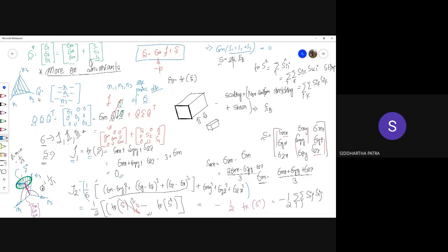So it's not the same octahedral plane, because this time we are not talking about microstructure. This time we are talking about a macroscopic representation. But again, the amazing thing is that in relation to plastic flow, in relation to plastic deformation, we are again stuck with one octahedral plane. It seems that the octahedral plane has a preference towards plasticity. So we end up having another octahedral plane.